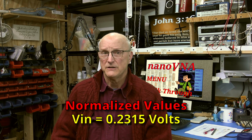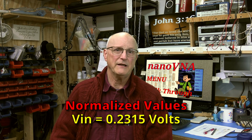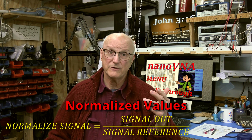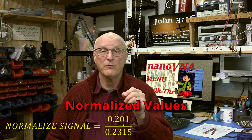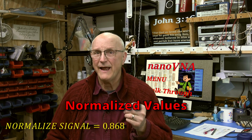So, if I'm using a 0.2315 volt signal as my source signal, and I'm looking at the other end of a cable and getting a 0.201 volt output, the normalized output signal would be, well, signal out divided by signal reference, which would be equal to 0.201 divided by 0.2315, so the normalized output voltage level is 0.868. With this very brief explanation under our belt, we can get on with looking at the various display formats. At the top of the list is log magnitude.